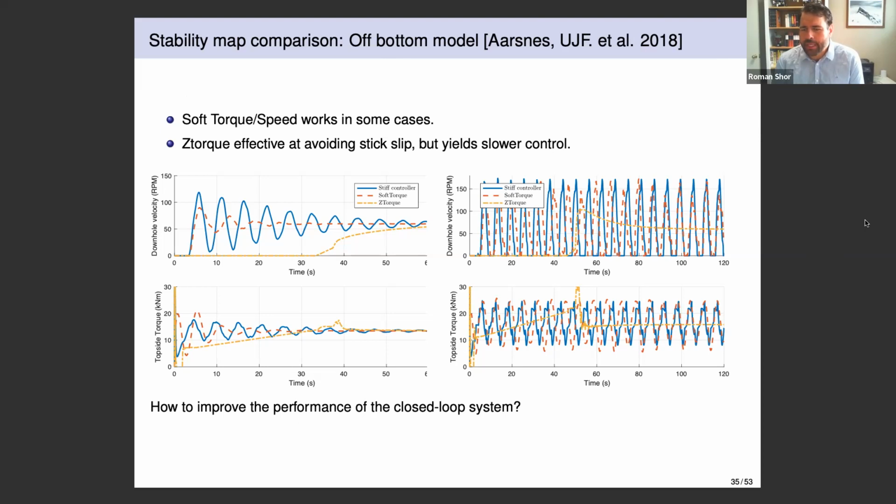I can go ahead and answer that one. We assumed we had a torque measurement at the drill pipe. We also had a motor inertia that we used so that we could subtract out the motor inertia torque. However, I agree with you. The actual field implementation includes filtering of your velocity sensor to give you a smoother acceleration. Plus, it has an estimator that gives you an estimate of pipe torque based on your motor torque, or your VFD torque that's being fed into the motor itself. Both of those loops are part of the Shell system, and they aren't directly part of the model, because this model is more of an idealized Z-torque rather than the field Z-torque.